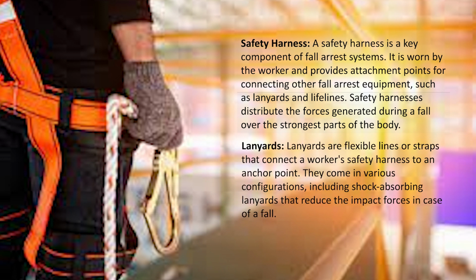Lanyard. Lanyards are flexible lines or straps that connect a worker's safety harness to the anchor point. They come in various configurations, including shock absorbing lanyards that reduce the impact force in case of a fall.